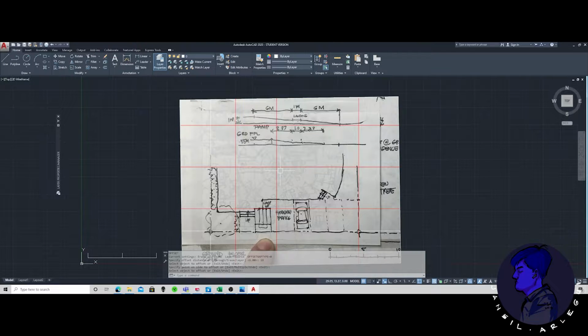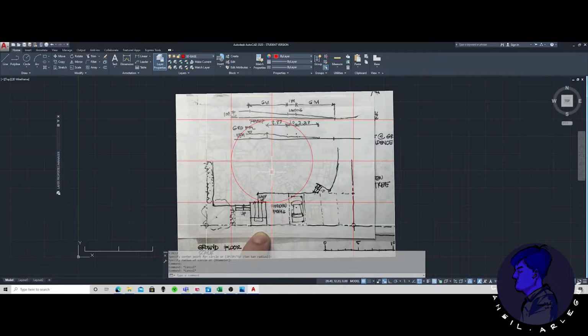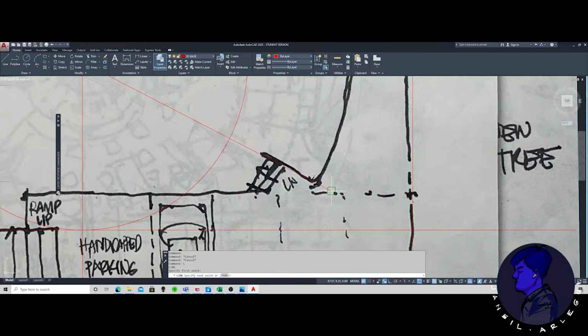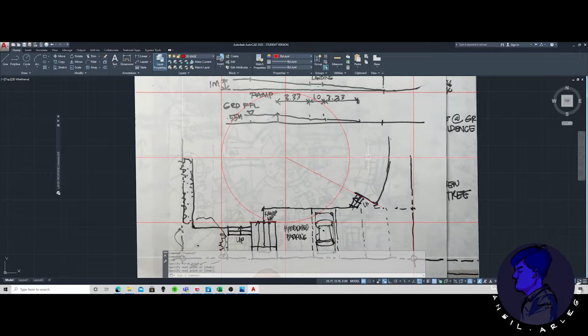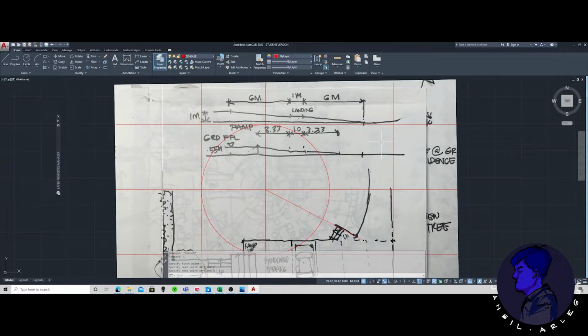And then the circle is generated from the center. So C for circle. Oh, I haven't changed this to that. You can always change this to that base layer. And then I'm going to create a line going here to there, a line to there, for my building. And I'm going to be offsetting this. Yes, this is a curving line from here for the building's line.